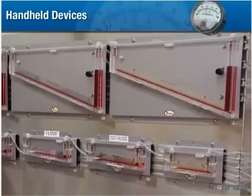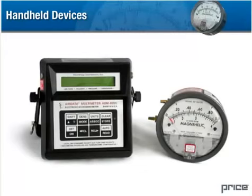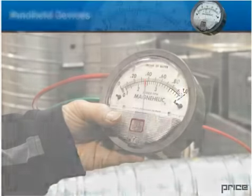When testing HVAC equipment in a laboratory setting, we make extensive use of inclined manometers to make air pressure measurements. While the manometer may seem a little low-tech, it provides highly reliable, precise, and reproducible measurements. However, due to its size and delicate construction, it may not be the instrument of choice in field testing. Handheld pressure measurement units, such as those shown, might be used instead to calibrate and evaluate HVAC systems in the field.